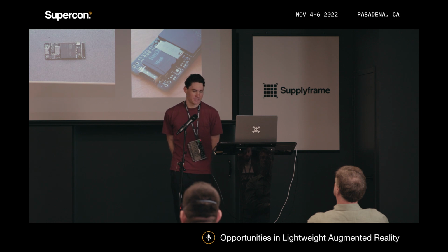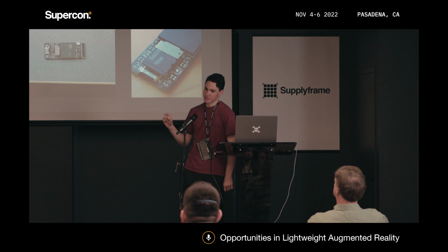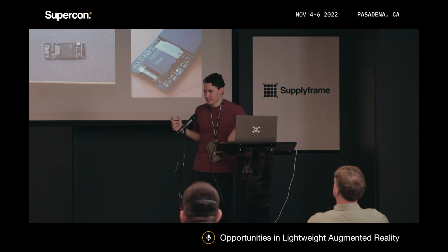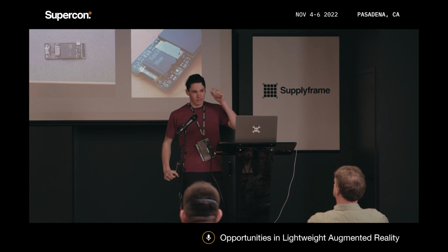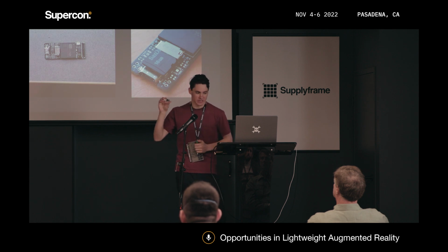So this is called OSD32MP1, and it has the STM32MP1 from ST Microelectronics. I designed this board just as an idea of, okay, what might you put in a glasses frame beside someone's head, what sort of electronics could you fit in this system in package sort of architecture.